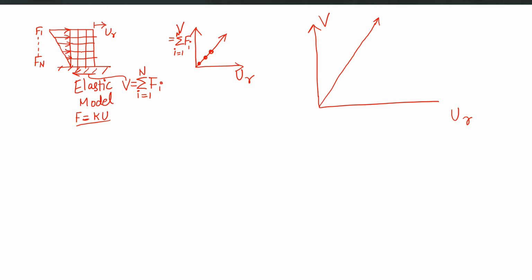Let's say the equivalent static forces, the representative forces of the future earthquake, because we can approximately convert the effect of an earthquake into some equivalent static loading, will have a very similar pattern because they are mass proportional. They will deflect the building in this manner. So let's say the equivalent static forces which the future earthquake can produce in our structure are somewhere here on the y-axis.